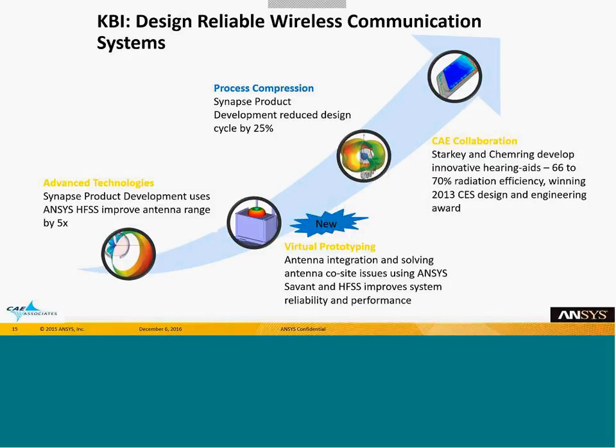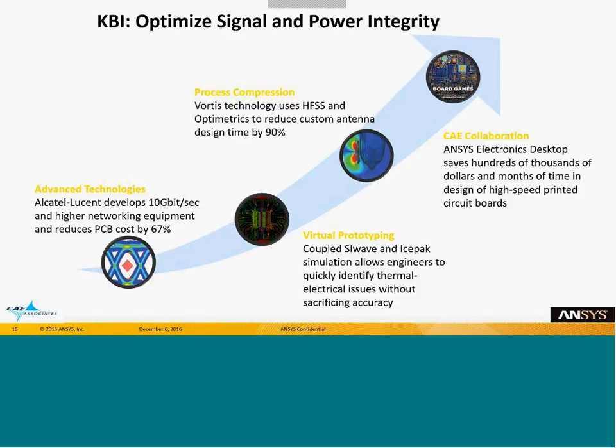It probably is not best practice to design an antenna in isolation and then put this in an entire system. So whether I put it singularly on a platform, or, this one is supposed to be the ear, whether I implant it in the human body, that's supposed to be a hearing aid there. You want to see how the fields are penetrating into the platform, whether it's metal or dielectric, right? How do the fields penetrate into your brain or into a part of your arm? And you want to take a look at what the field pattern is. What is the radiation that's being emitted out of that device? Okay, so we can go from the component level all the way up to the system and characterize the field patterns or the transmission in a system type of application.